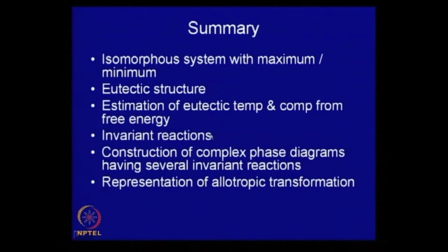Then we looked at several invariant reactions, and broadly these invariant reactions have been classified into two groups: one in which a particular phase dissociates into two at a particular temperature, and the second category, in which two phases react together to form a third distinct phase on cooling.